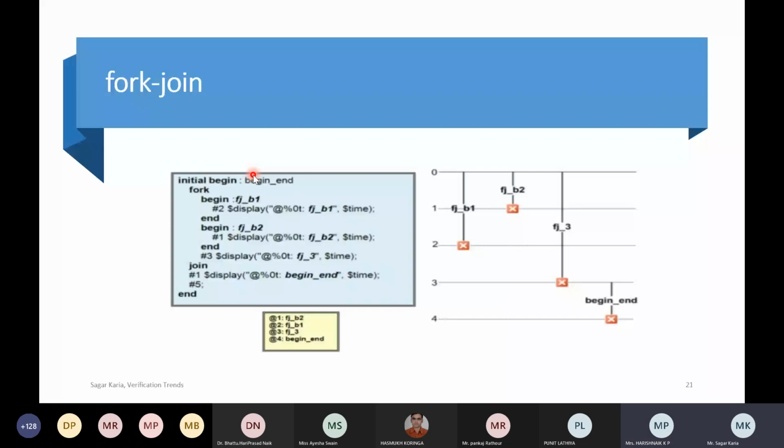And how do you do that parallelism within a language? With the help of fork join, you start a USB, you start your graphics driver, you start your I2Cs or SPI devices, or your mouse, keyboard, whatever. So all those threads would be forked simultaneously and start concurrently. So that is where this is useful, which is not present in Verilog.